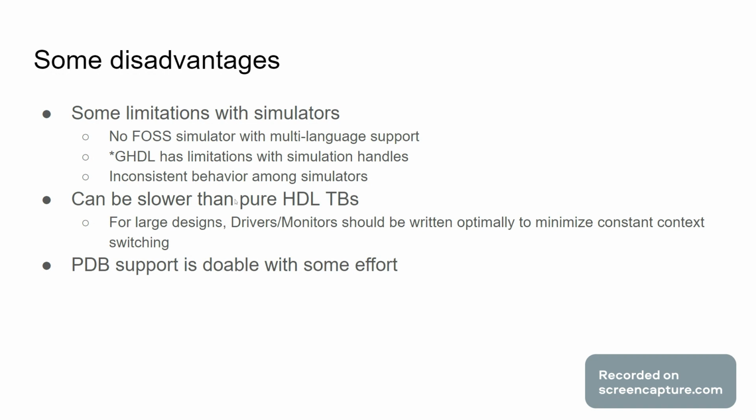And then one disadvantage that's definitely worth mentioning, because I know some people are going to ask about it, is, well, can you use the Python debugger? The answer is yes, you can. But there is some bit of effort that you need to put into it. I'm not going to get into it here, mostly because it's been a while since I've used the Python debugger with cocotb. But it involves starting the simulator first, since the simulator is actually the one in control.